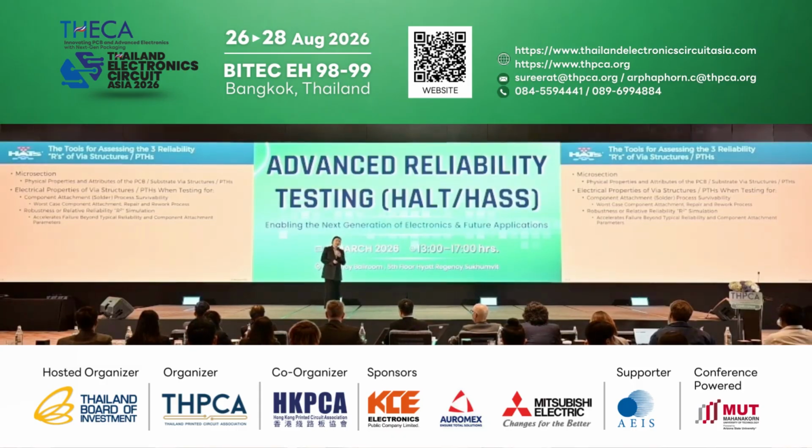And there's another concept called robustness or relative reliability, what we call R-square simulation. This robustness testing or relative reliability R-square testing actually considers accelerated failure factors that can cause the product to fail a lot faster than in real life.